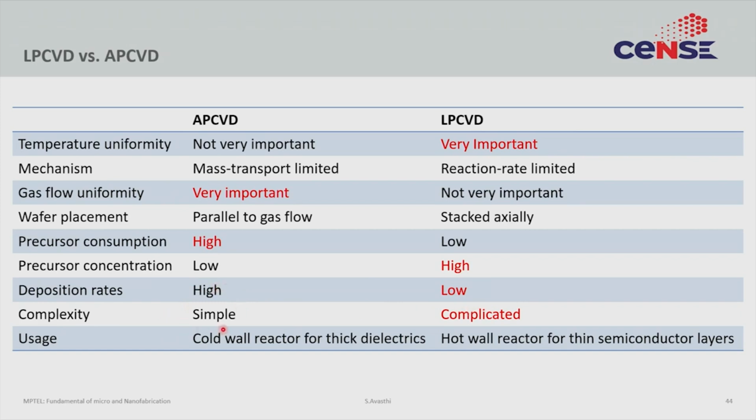APCVD reactors are much easier to construct because of the lower pressure, the pumping, the reactor design, the Reynolds number design, etc. LPCVD becomes a little more challenging to make. Often these are used for semiconducting depositions, often APCVD is used for dielectric depositions.